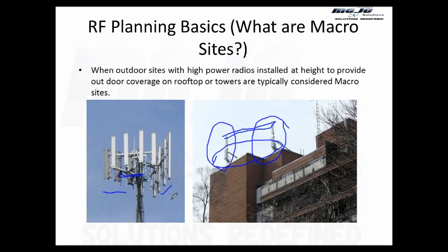What is combining and duplexing? We'll discuss it. You will be able to understand what I'm saying. So after combining and duplexing, there were a minimum of 4 antennas. You didn't want to combine or duplex more because combining and duplexing has a loss of up to 3 to 6 dB. You do not want to introduce the loss, and that loss will come in both uplink and downlink. Especially for uplink, which is more power sensitive, you could not do that.